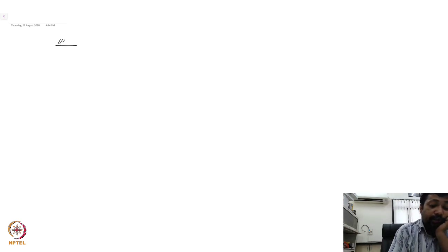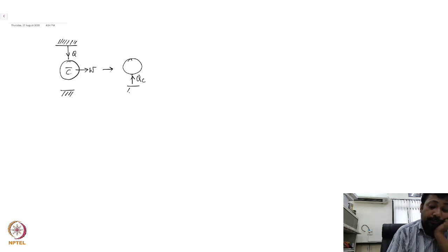The other way around is when you violate Kelvin's statement. So let's violate Kelvin's statement on purpose. I have a machine, which I denote by a bar because again it's violating a statement. It draws an amount of heat Q from the hot reservoir and does an amount of work W, completely converting this heat into W, which violates Kelvin's statement. Now this work I can use to drive a refrigerator. A refrigerator would take up a heat QC and would dump a heat QH. So this one violates Kelvin's statement.